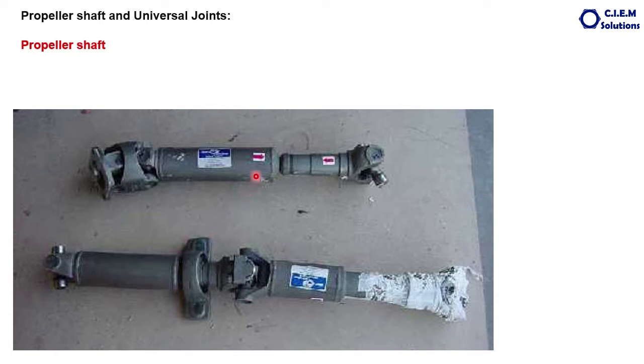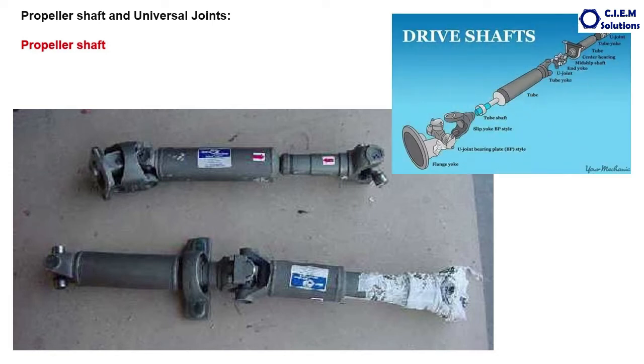And the quality of the steel and the welding process adopted in manufacturing the propeller shaft should possess greater resistance to the sag or misalignment, and the quality of the welding and the quality of steel used in manufacturing the propeller shaft should possess good torsional strength. And also the shaft should possess low resistance or low inertia to changes in angular speeds, because the propeller shafts in the vehicles do not run at constant speeds. Propeller shafts always run at variable speeds. This is how it looks.